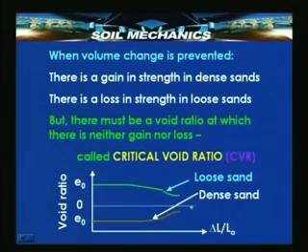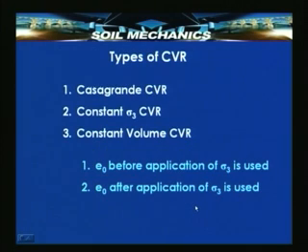axial strain is such that no volume change takes place, and that means that this void ratio is a critical value at which neither gain in strength nor loss in strength is there, and the soil is neither dense nor loose, and it is this void ratio at which volume change does not take place, and therefore soil undergoes liquefaction during shear. This void ratio actually is defined differently by different persons.